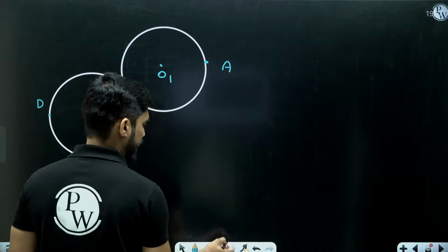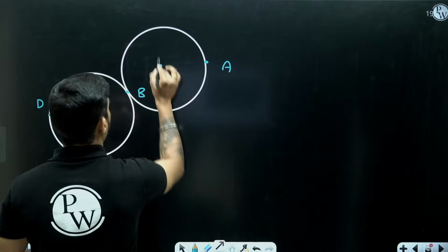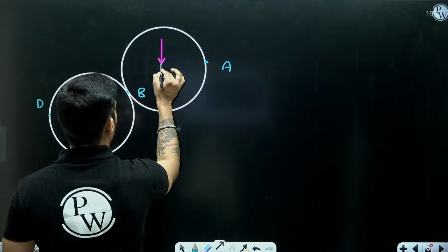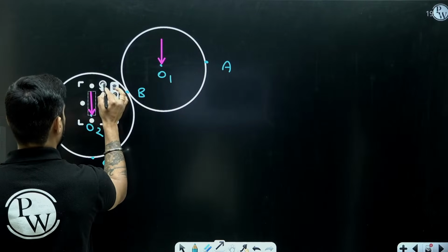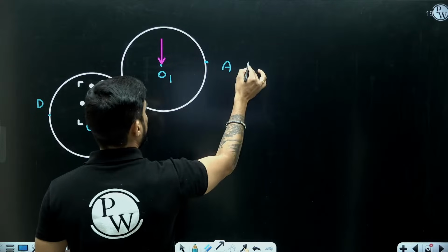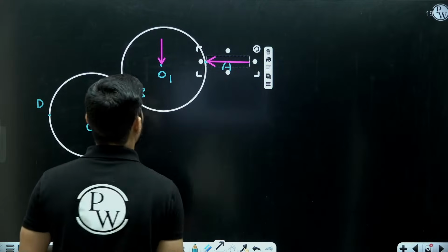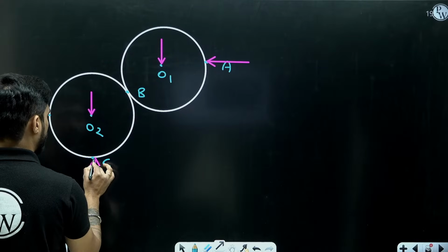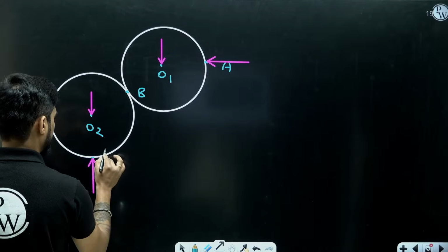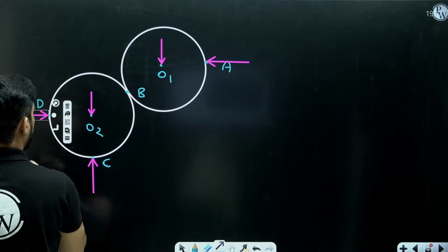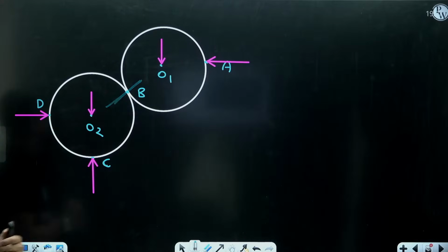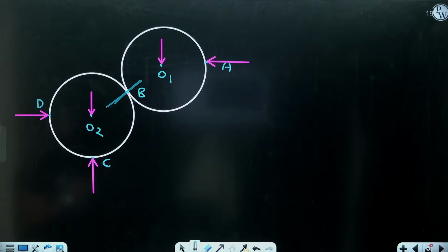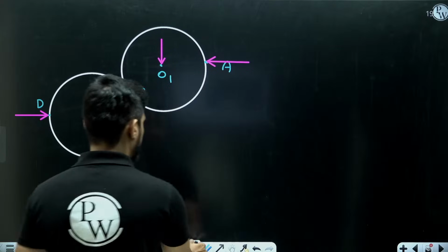So now understand what will be the forces. Weight of both the spheres, 100 Newton acting at their center. One reaction here which I have already calculated, one reaction here which will be vertical, one reaction here which will be horizontal. I don't need to consider the reaction acting at B. Equal and opposite reactions cancel each other.